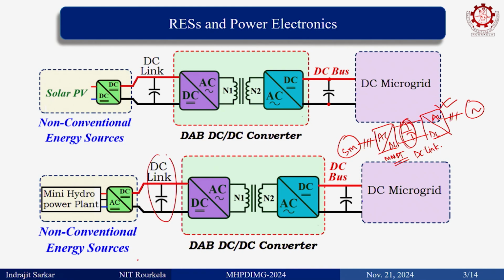So, we need to regulate this DC link voltage, and this is already regulated as it is the DC bus voltage of a microgrid. Previously, with the back to back converter from the grid, we were able to regulate it. Now, we have a DAB DC converter. The DAB converter cannot regulate this output DC voltage, if it is SPS. That I will come to.